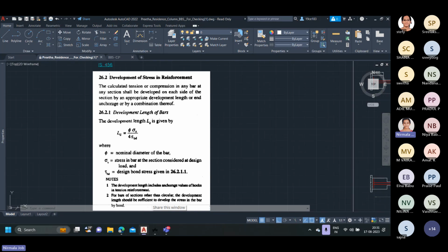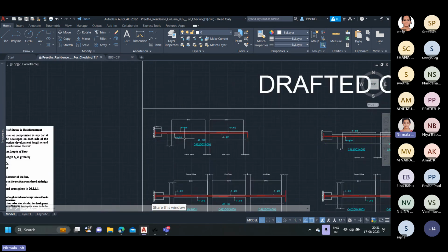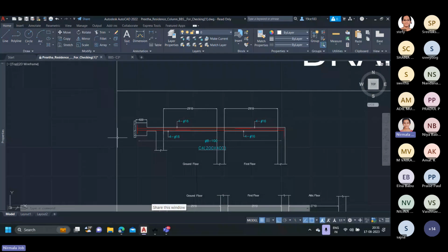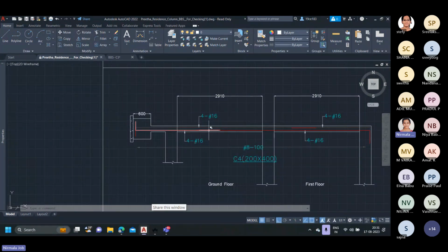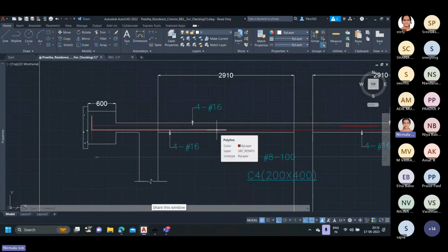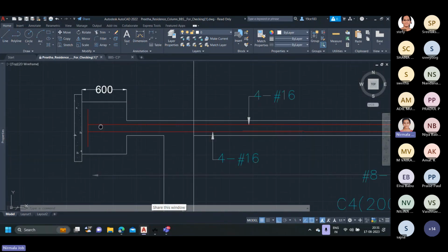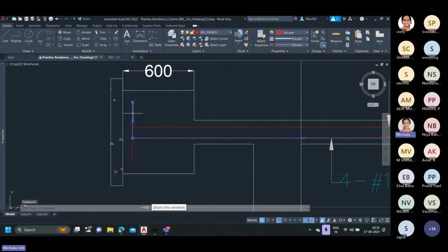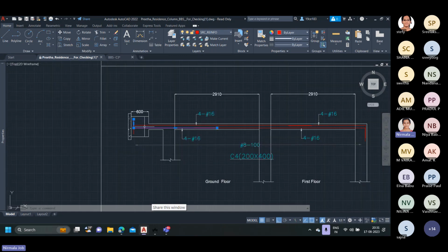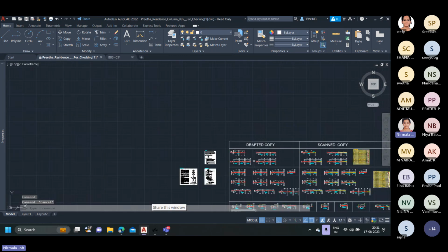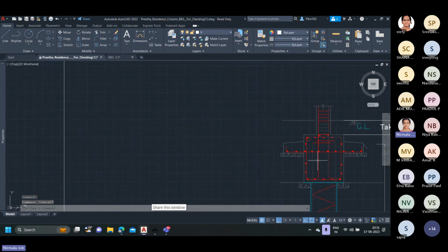It is already familiar to you from the previous classes. This is the same equation which we use for development length and lapping areas. If the development length is not sufficient to provide a bend like this, we'll need to provide a minimum vertical leg of 300 mm, as shown in this figure.